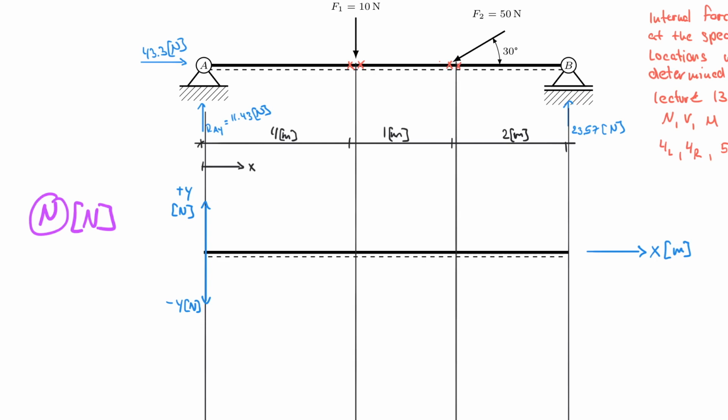So what I'm trying to tell you is we have an XY graph which mathematically looks normal, and you may wonder, why do I emphasize this so much? I'm emphasizing this because the reason this is a normal mathematical graph with X and Y is because we have the reference fiber on the bottom. If the reference fiber was on the top, we would actually look at a Y-axis pointing positive downwards and an X-axis pointing positive to the left.